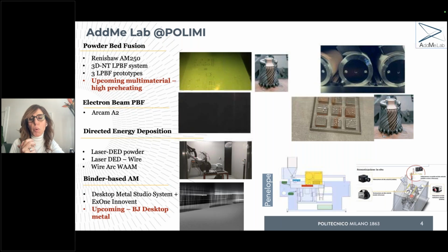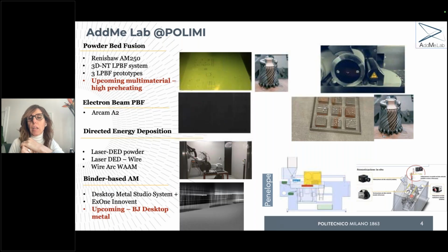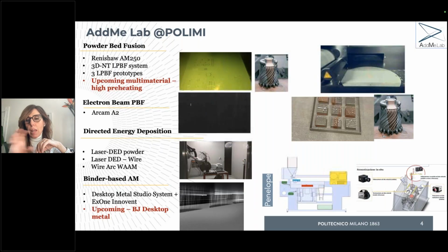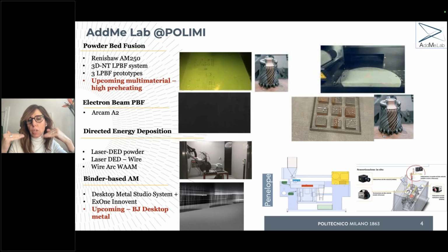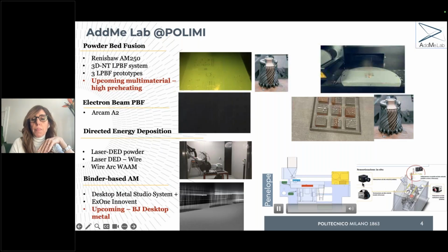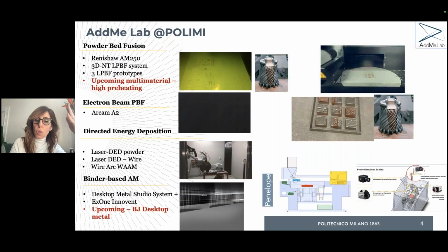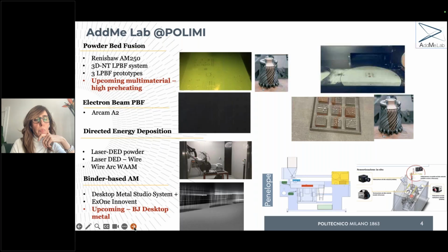For instance, this was a prototype that was developed and patented a few years ago, and the aim was the perfect machine. This yellow box that is going back and forth is supposed to cancel the defect, since the idea of additive manufacturing is that layer by layer I'm building a part. The main idea of Penelope, this prototype, is that when I see a defect at a given layer, thanks to all the cameras, and we will discuss all this sensing, what should I do? I can first of all stop, avoiding building a huge part that is defective. But on the other side, I can maybe even correct the problem, erasing the last layer with the defect and starting again going up. So at least in principle, I should be producing parts without defects at all: zero defect manufacturing.